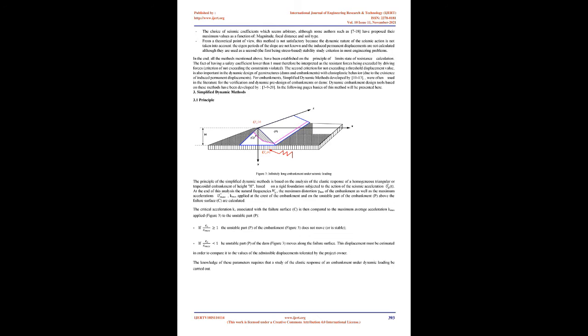From a theoretical point of view, this method is not satisfactory because the dynamic nature of the seismic action is not taken into account, the eigenperiods of the slope are not known, and the induced permanent displacements are not calculated, although they are used as a second criterion, the first being stress-based, in the stability study in most engineering problems.